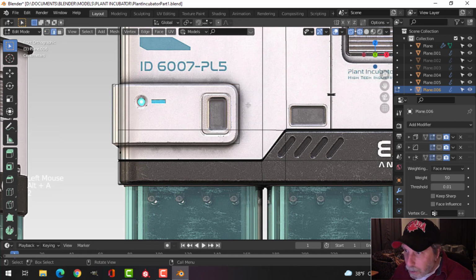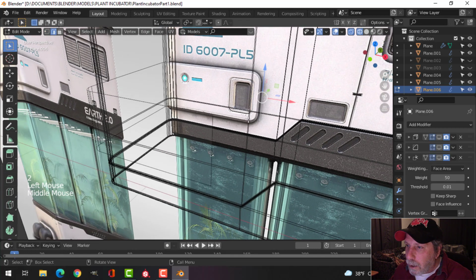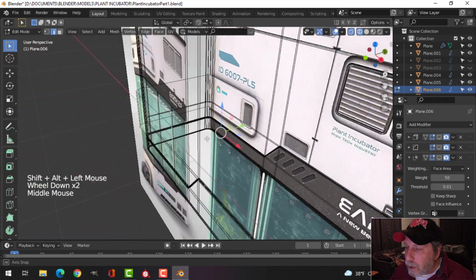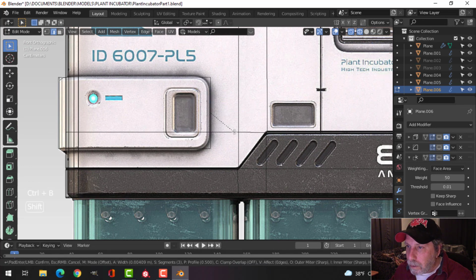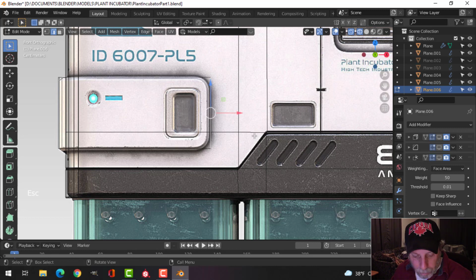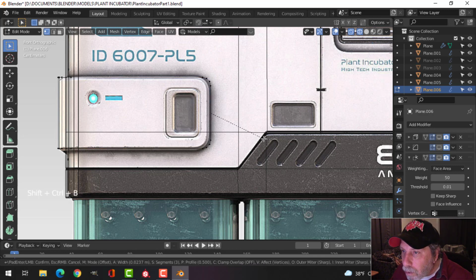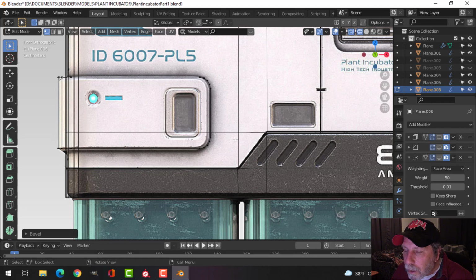And what I'm going to do is I'm going to select that edge and that edge. Yep. And I'm going to Control B. No, I'm going to Shift Control B actually to bevel that. And I'll press 1 to go into, no I won't. Alright, let's do it in vertex selection. It's easier to see. Shift Control B, pull, and I'll put another vertex or 2. 5 is probably okay. Just like that. Okay.